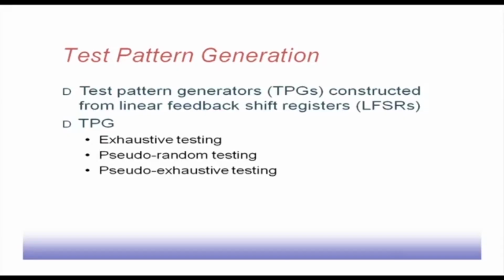While doing the test planning part, we had assumed some values for those points, but in reality when it operates, it comes up with some other values. So, if the values are unknown, then the values may be different. As a result, the final response, or the golden signature, may not match with the response that we get from the circuit under operation, and even if the circuit is correct, it will be identified as a faulty circuit. So, that is why all these X's need to be blocked, and this clock skew problem has to be solved. Next, we look into the test pattern generation process.